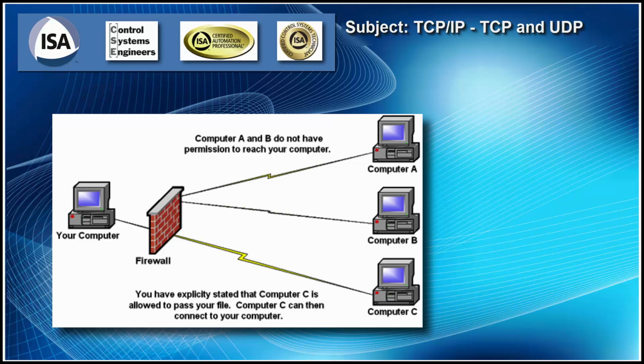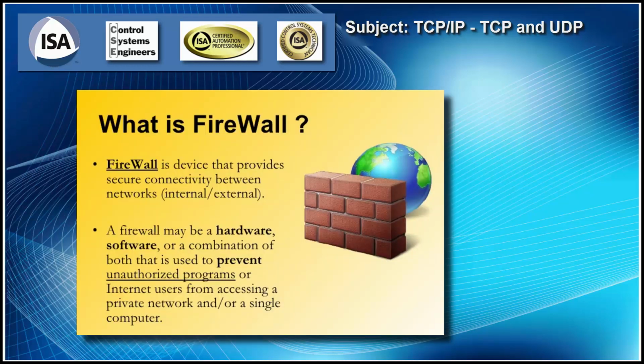And this also works on your wireless networks as well. You can keep certain PLCs out and only certain PLCs get in. As a matter of fact, when you're setting up a workgroup bridge, you'll use the MAC address of the workgroup bridge and it will go into the access point so it knows where it's coming from. In other words, who the access point is talking to, and it is really the workgroup bridge. And then the workgroup bridge will have the MAC address of the access point, so it knows it's only that access point that it's talking to. This helps to provide security, and it gives us a path to go back and forth with our communications.